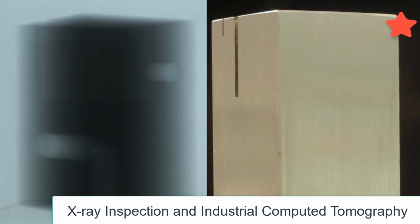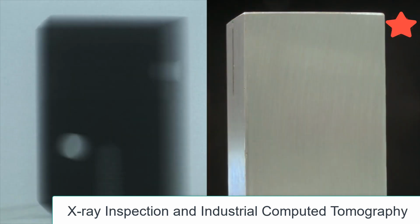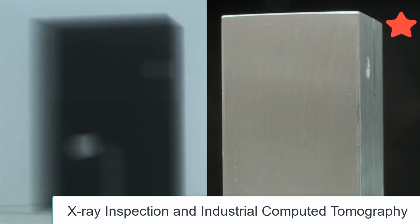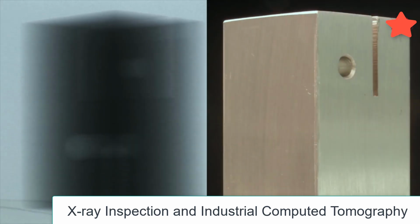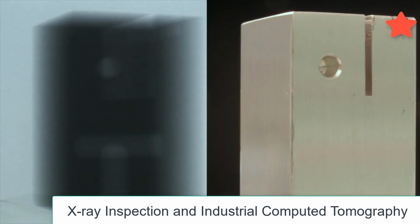The X-ray images are displayed in real time on the computer monitor. As opposed to classical X-ray images, they are shown as positive images. Thick areas and areas free from defects now appear dark. Thinner regions, or regions with defects, appear light. The drill holes and the different saw cuts are clearly visible.